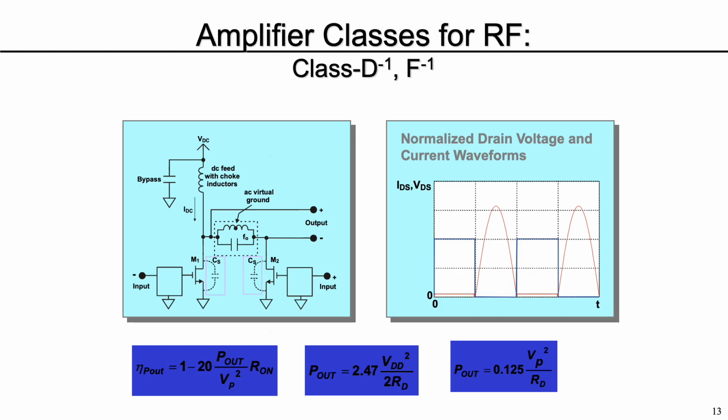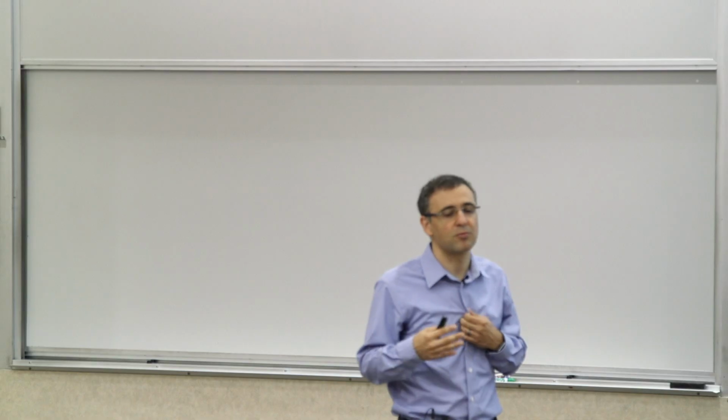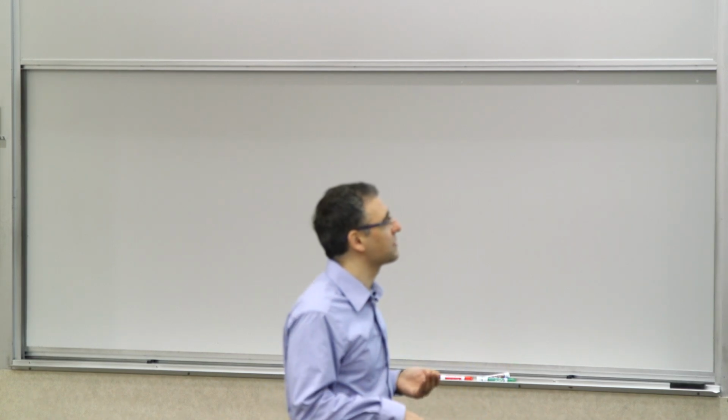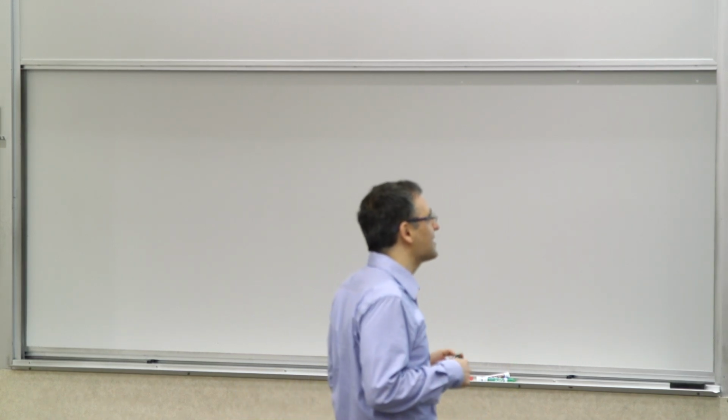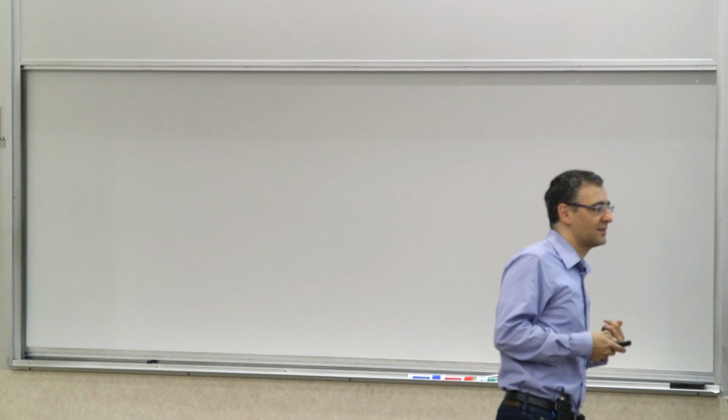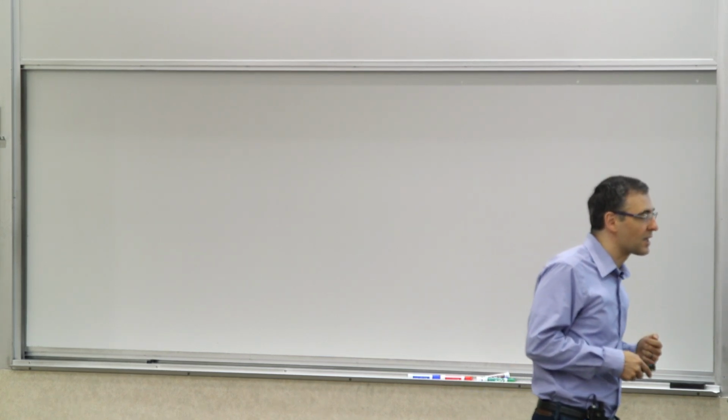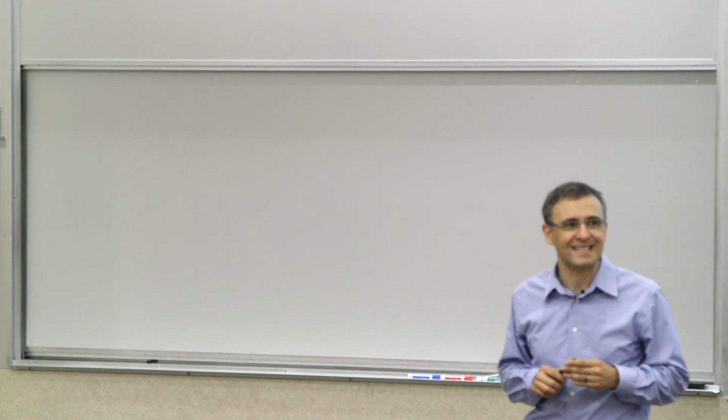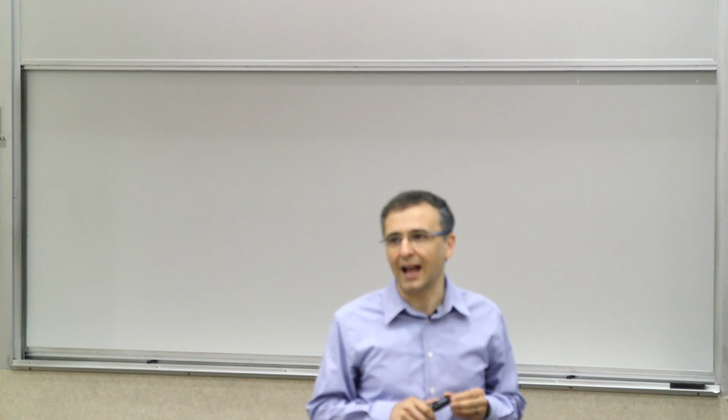And what looked like a current waveform becomes a voltage waveform. So now the question is, how can you make something whose current waveform looks flat like that, and the voltage has that other shape? This is actually in a way easier because, for example, if you have a differential one with a balanced, properly tuned load, you can create this kind of current. Now, this is useful because of certain things that we'll see next, which is another class of amplifier, class E, which is an interesting class.